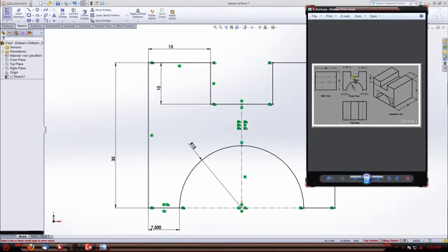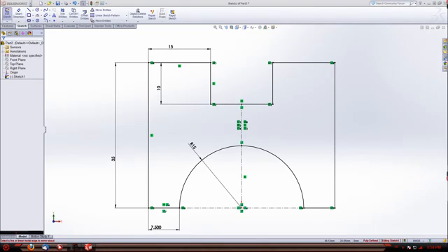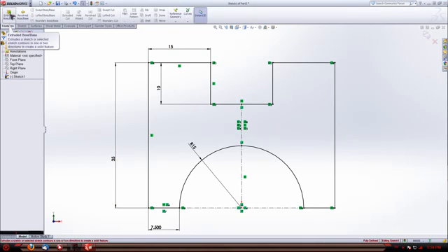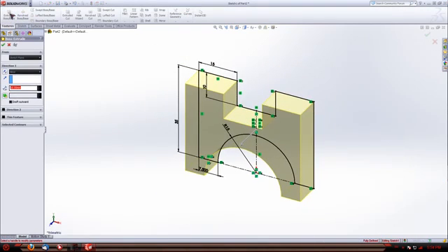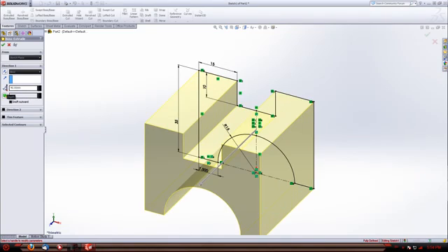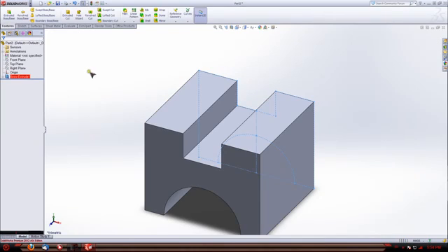You can see I've got it drawn right here. And next we need to extrude it 40 millimeters. So I'm going to go to Features, Extrude, and right here lets me define the distance I want to extrude it. 40. I like that, so I'm going to hit enter.